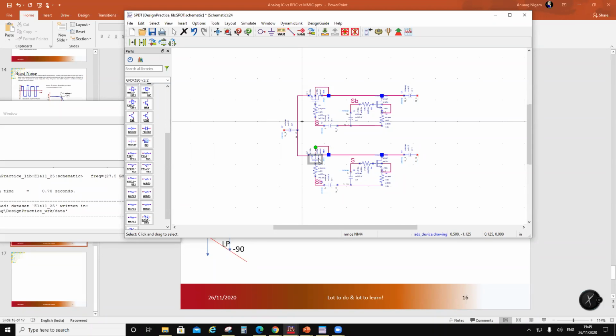But then if this goes large and it is off, in reality it is not off. Why? Because the output capacitance is large now, since you chose a large pass element. When the output capacitance is large, even if this device is off, there's a coupling between 1 and 3. So your off isolation is bad. Your on isolation improves because you made the pass element big, but your off isolation has degraded. It is supposed to be high, but it is low because now the output capacitance is large.